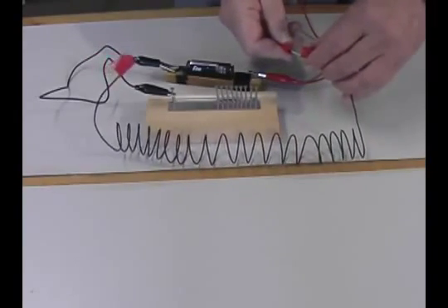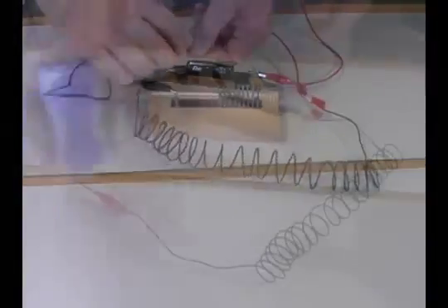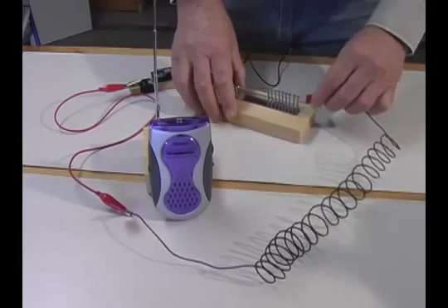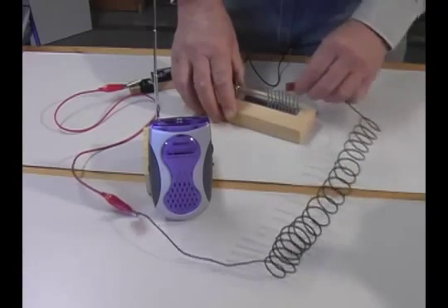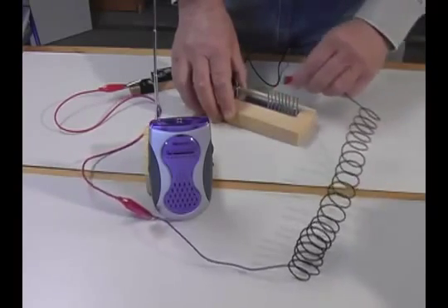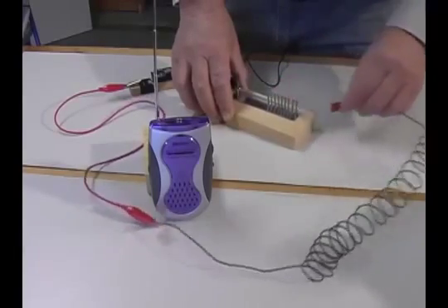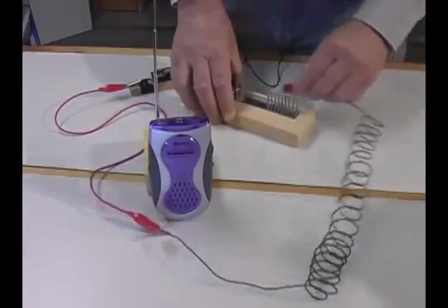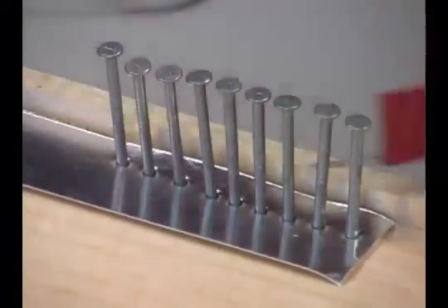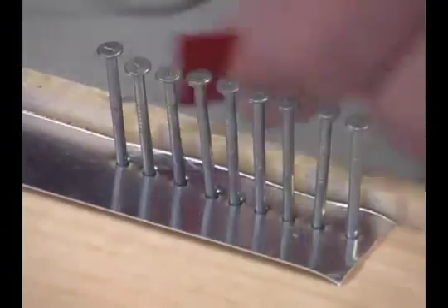Connecting one end of the battery to the antenna, we are ready to transmit. Again, tune an AM radio to a blank spot on the dial and turn up the volume. Sliding the available antenna wire along the row of nails creates a buzz on the radio. As the wire moves across the nails, the circuit is alternately completed, then broken, each contact sending a pulse of electromagnetic radiation.